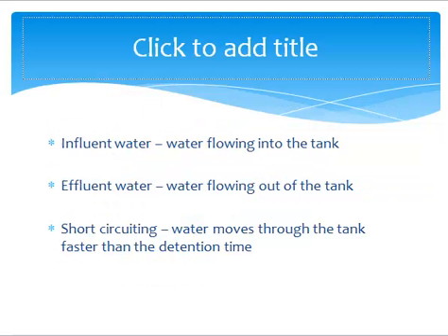A few additional notes about settling tanks are the terms influent water, effluent water, and short-circuiting. Influent water is water that flows into the tank, while effluent water flows out. Short-circuiting occurs when water moves through a tank faster than the detention time. When this occurs, sedimentation may not be able to complete.